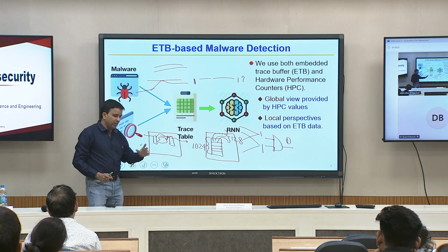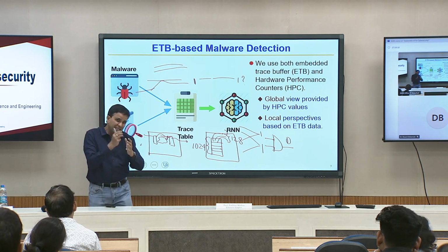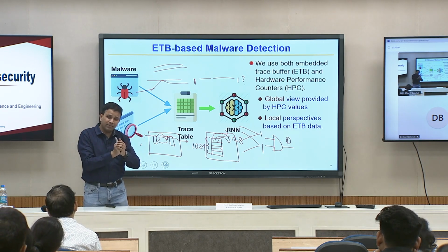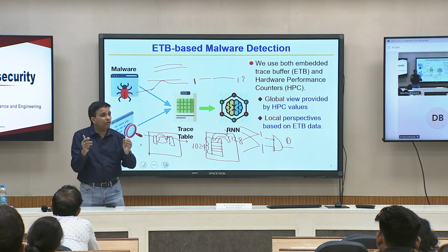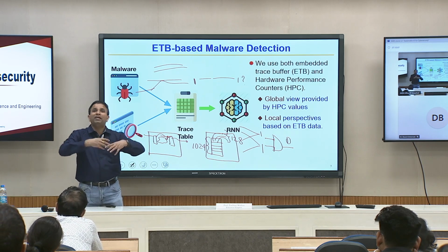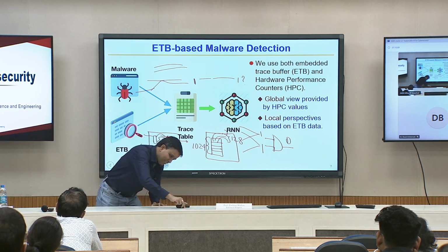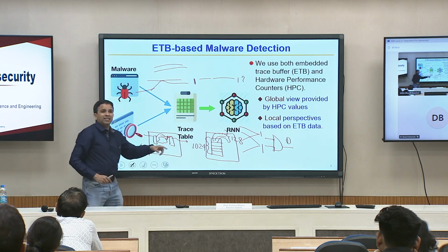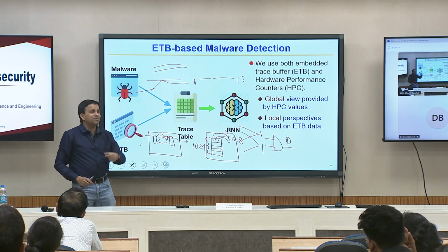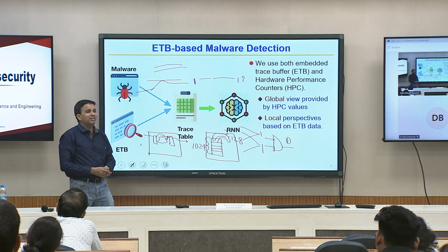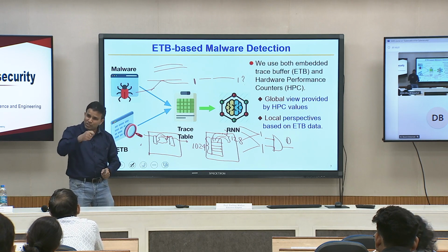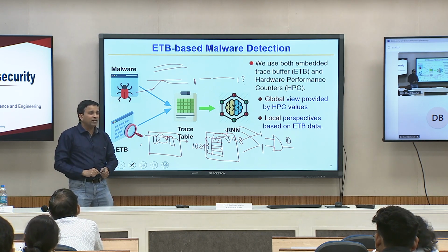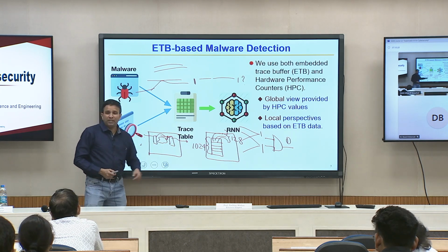Normal execution is going on. Remember, in normal execution, the key which is used for encryption and decryption will travel through the system, and there would be a point when the key would be completely out in the open right here, which is right in the scan chain. That 128 bit key or 256 bit key would be right in the scan chain. If an attacker can stop execution right then and there and change the setting of the chip to manufacturing mode, they will be able to dump it from that scan chain.